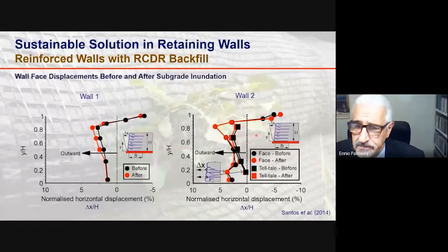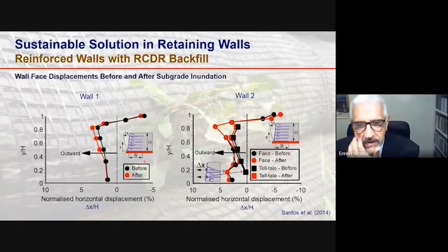But in wall 2, because of the bulging of the reinforcement, due to less confinement of the geotextile, you will get greater horizontal displacement. But if we look at the horizontal displacement a bit inside the reinforced mass, where you have an increase in the tensile stiffness of the geotextile, you see less horizontal displacement in that region and values comparable to those obtained in the geogrid reinforced wall.